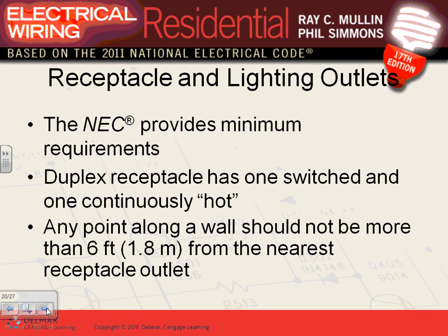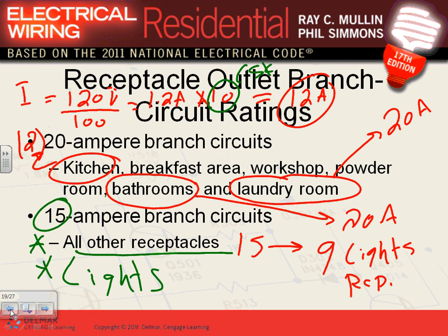Just a quick question. For the lighting circuits, is that or is that not considered continuous? Non-continuous load. Non-continuous, because residential is non-continuous. So we really could load that up to 15 amps. I guarantee you, it's not a good design though.